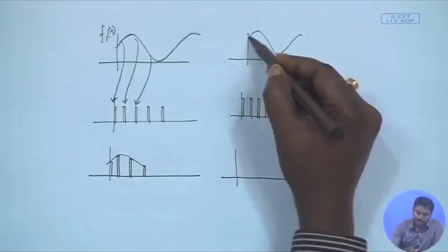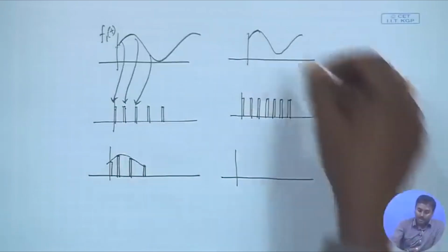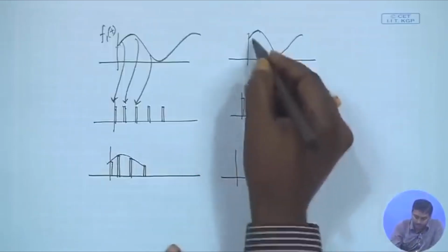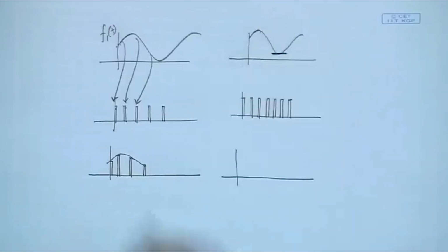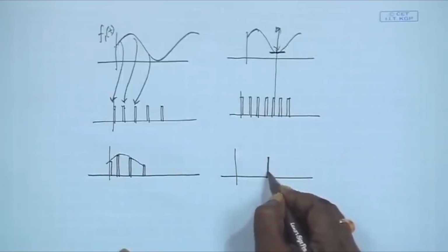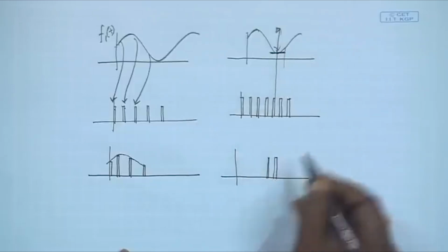And my mechanism of modulating this width is, as I see an increase in the signal amplitude, I either increase or decrease the width of this pulse. Okay. So basically there should be a minimal width which refers to the minimal part of the signal. And accordingly I will be varying the width from here to here. There will be some scaling of varying the width. So let's say this is the minimal part. Here the pulse should be of minimal width, and then whenever it increases, here it increases slightly. So the pulse should be a little bit wider.